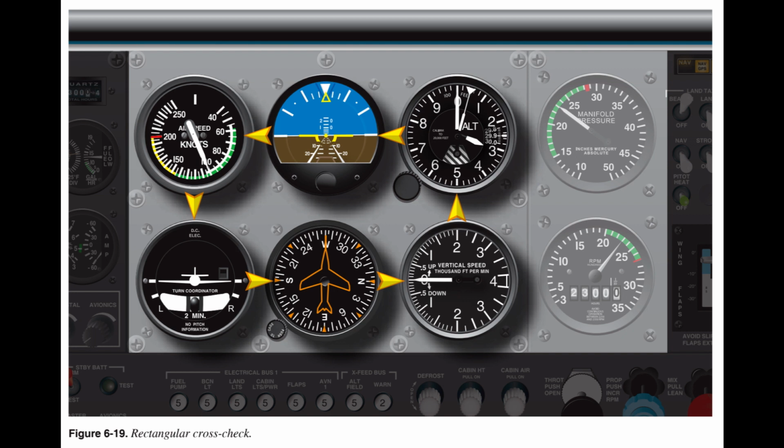Fixation, or staring at a single instrument, usually occurs for a reason, but has poor results. For example, a pilot may stare at the altimeter reading 200 feet below the assigned altitude, and wonder how the needle got there.